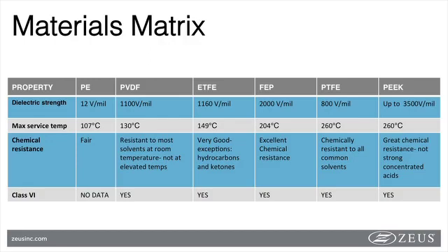There's truly a world of possibilities with heat shrinkable materials. Here we have a comparison of different materials, ranging from lower cost, remedial performance, all the way to more costly but extreme performance characteristic materials. On this slide, we are comparing polyethylene to some of the fluoropolymer family heat shrinks, as well as PEEK shrink. From the material selection standpoint, it is important to know what performance attributes are essential to your application. Here we have summarized a few of those.